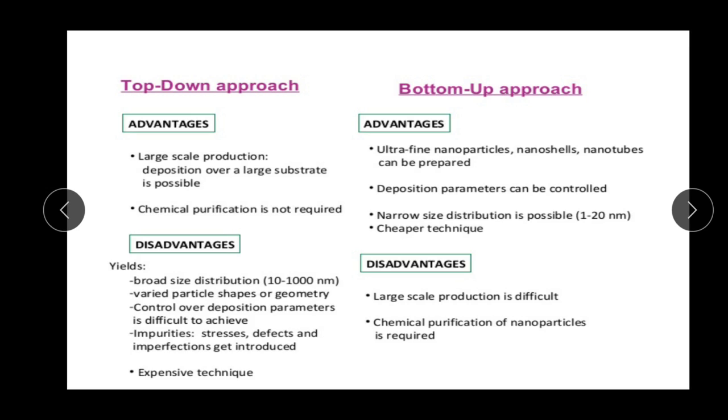Chemical purification is not required. So, the disadvantages of this top-down approach: the broad size distribution, in the range from 10 to 1000 nanometers; varied particle shape or geometry; control over the deposition parameters is difficult to achieve; and impurities, stress, defects, and imperfections get introduced.